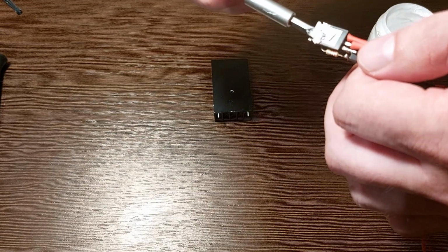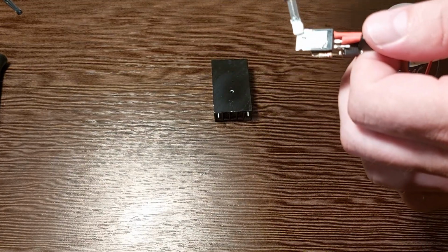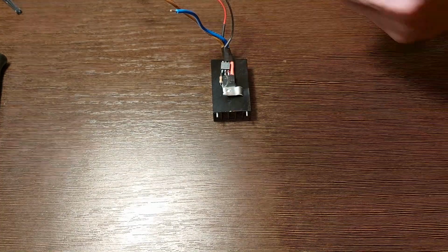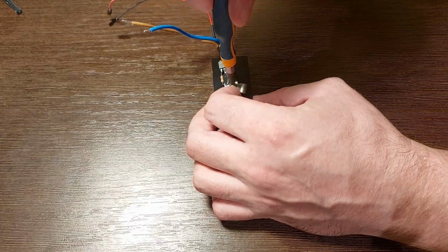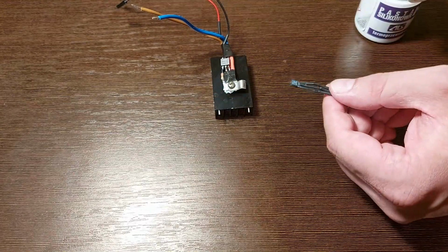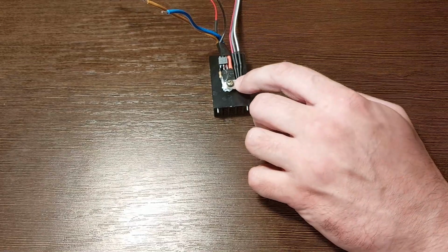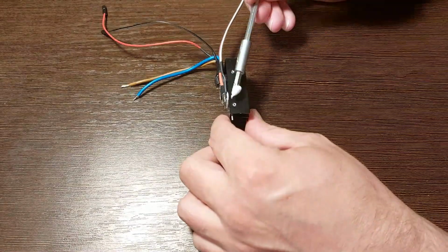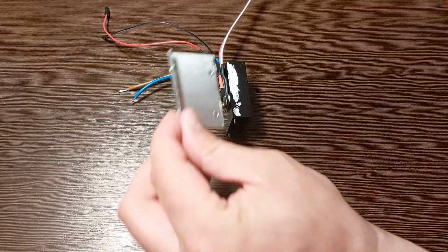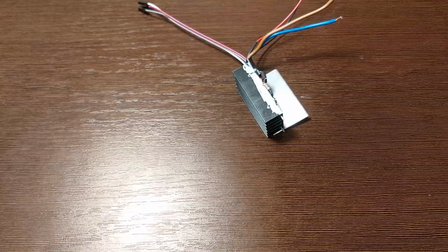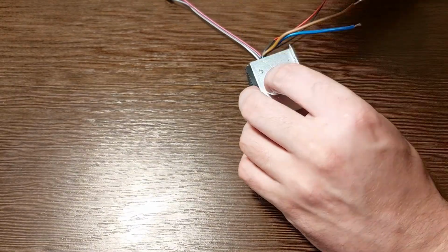I apply some thermoconductive paste to the triac pad and mount it on the radiator. I also use a small stainless steel plate to install a simple thermometer. It's totally optional, but I just want to make sure I have sufficient cooling. After tightening the bolt, I can add supports for the radiator. I made them of 0.5mm aluminium plate, so they will act as additional heat sinks.